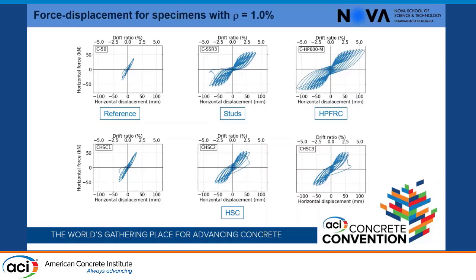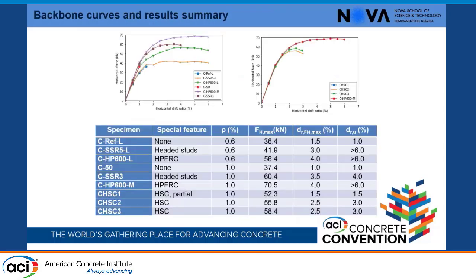For the high-strength concrete, as I referred before, the first slab, with only a small layer at the bottom, didn't work out for the cyclic loading and failed at a small drift. The other two solutions reached 3% drift, which is a good drift for horizontal loads.